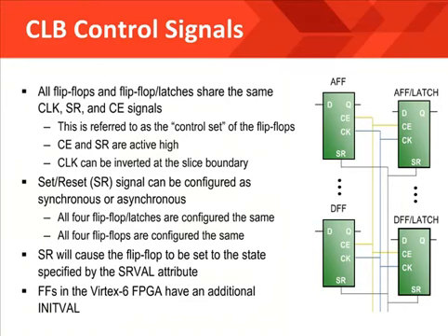The set and reset signal can be configured as synchronous or asynchronous. For synchronous design purposes, Xilinx recommends that unless absolutely necessary, your design should use a synchronous set or reset rather than an asynchronous one. We discuss good synchronous design practices in the Essentials of FPGA Design course.